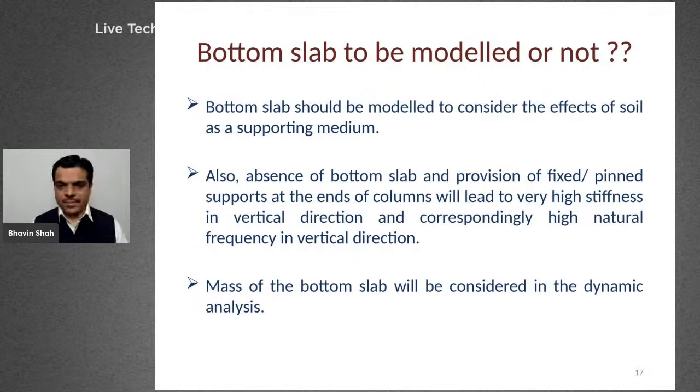One more question, which was asked by a few engineers, is whether the bottom slab is to be modeled or not. According to me, the bottom slab should be modeled to consider the effect of soil as a supporting medium. When we model the bottom slab, the mass of soil can be considered for the dynamic analysis, because the soil on the bottom slab also contributes towards the mass of the entire system.